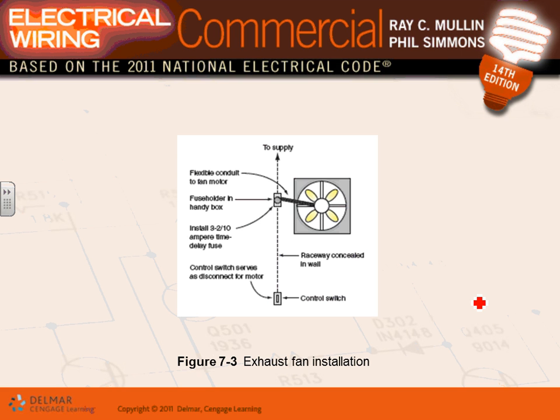Here's an example. Here's my fan coming in, we're supplying it, and I have a controller here. That acts as a disconnect for this fractional horsepower motor. Are you guys familiar with fractional horsepower? These are less than 1 horsepower. These are little horsepower machines. The smaller the horsepower, the less dangerous the equipment is, so you can use a snap switch like this one to disconnect them.